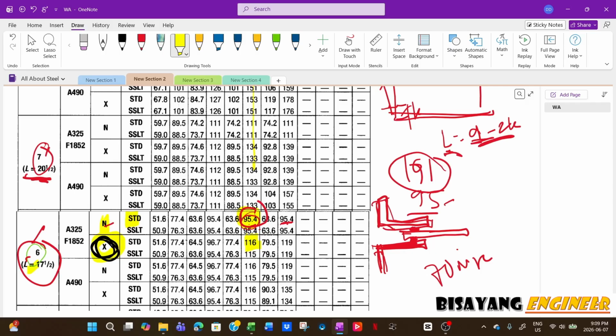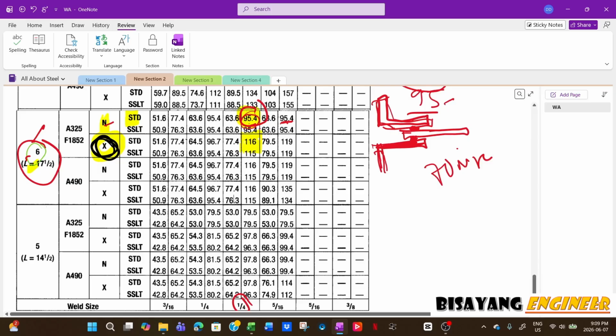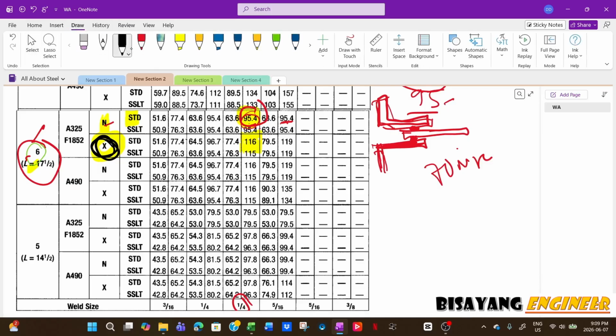So it's more of a quality control now. You have to make sure that when they submit the shop drawing, the bolts have enough room, it's not threaded all the way to the head. If you will use the threads-excluded value, then you just have to make sure that when they submit the shop drawing, you have a washer here, right?